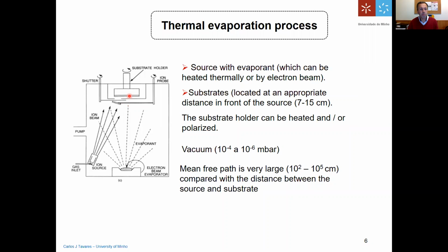And if you compare this with sputtering, which I'll be giving you some insight on in chapter 3, this can be 500 times less than the case of sputtering, which means that the particles will not hit the surface with a lot of energy. Actually, the energy is very low, and so these atoms will not have a lot of energy to look for the best position to nucleate. So this is actually one of the disadvantages of thermal evaporation.